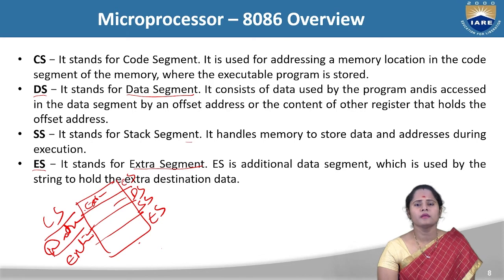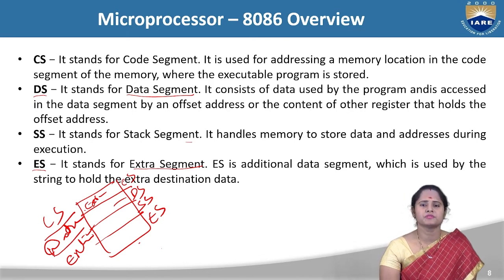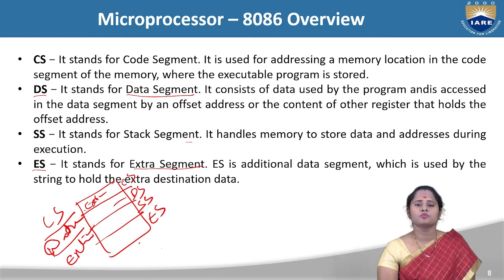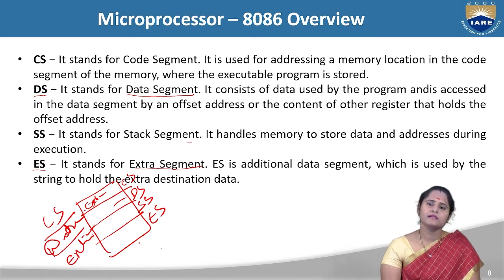So what is happening here? The searching time for my microprocessor is reduced. My microprocessor knows the code I need to execute is in the code segment, and the stack is in the stack segment, which I can take and execute. Whatever content is related is already stored in the related memory locations, so it makes my processor function faster, right?